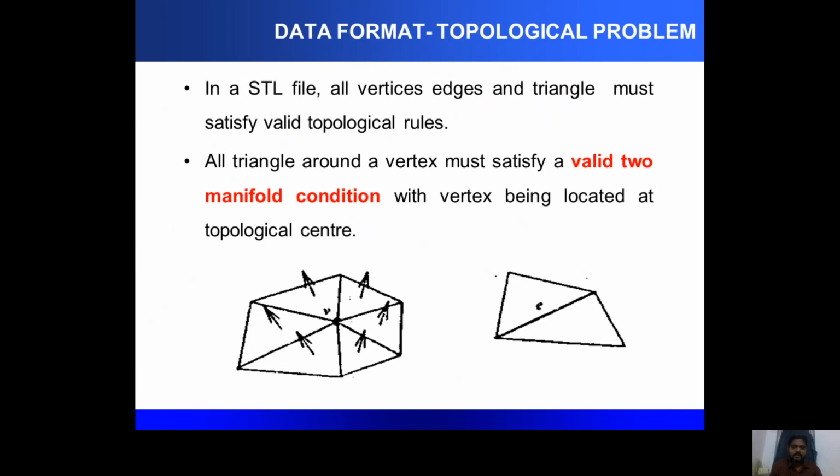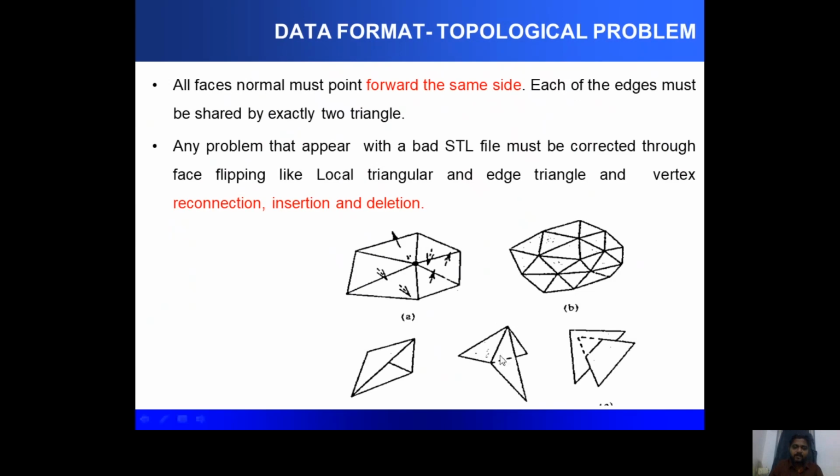In that case, there might be a problem in terms of normal vector generation, and this problem leads to overlapped triangles or multiple-edge triangles. So we may not have a normal vector, and this leads to degenerated or flipped triangles. This has to be corrected manually. Some software has an automatic algorithm where you can fix this error. Another important geometric problem.